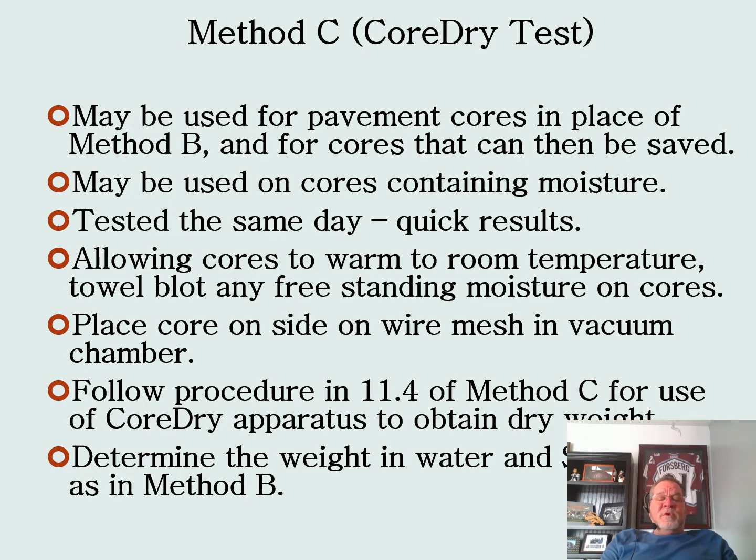It's best used for in-place cores or cores from a roadway. You have to allow the cores to warm to room temperature, blot them with a towel, put them in the wire mesh basket in the vacuum chamber, and run that following the manufacturer's recommended procedure.